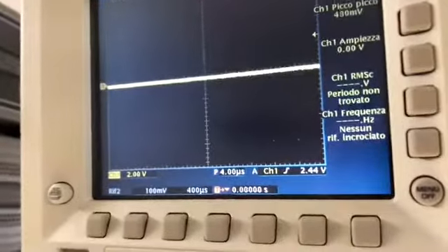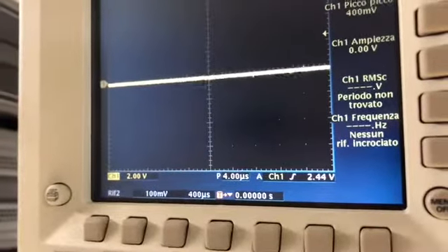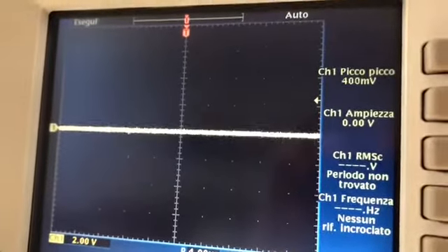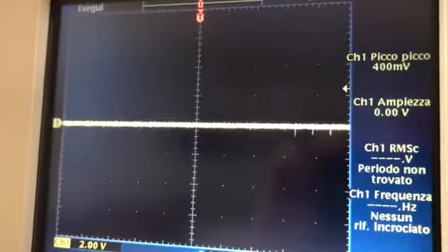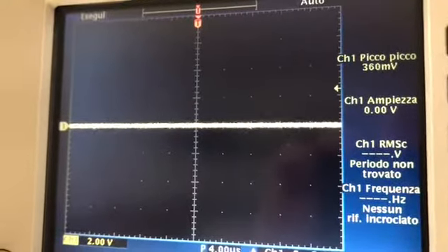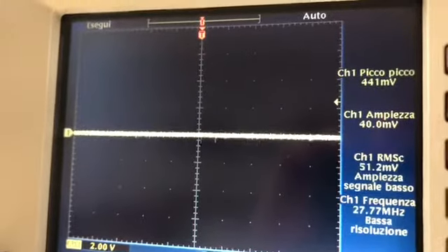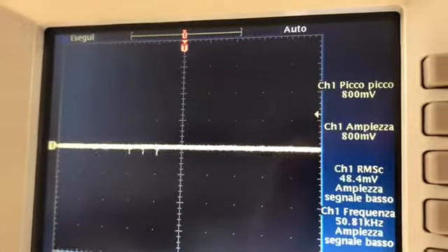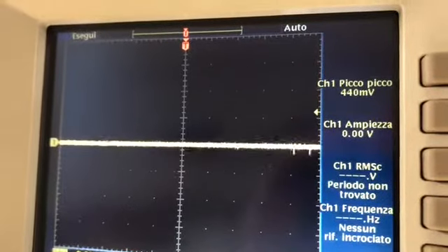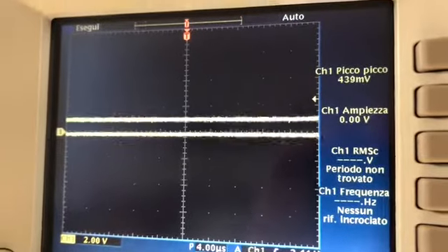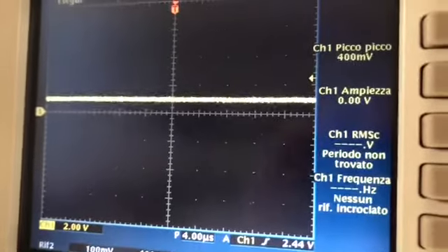I'm going directly on the scope. So this is what I have found, this is the input. So pin 3, 1, 2, 3. Okay, so nothing. It's just some small sparks, but glitching. It's at 0, a logic low level. If I'm going to the output, I should find a high level.